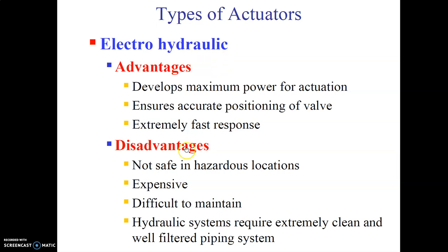Now what are the limitations? Since the medium is oil, it is not safe in hazardous area. For the same reason it is expensive and lot of maintenance is required if it is oil, and cleanliness is required because the piping system should be cleaned regularly.